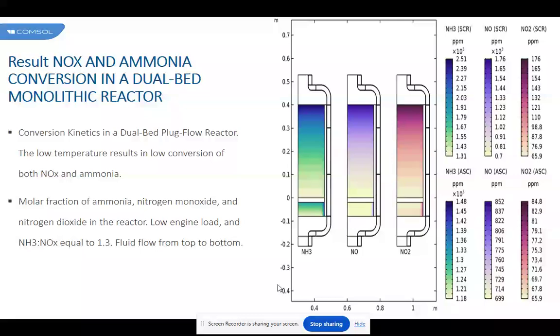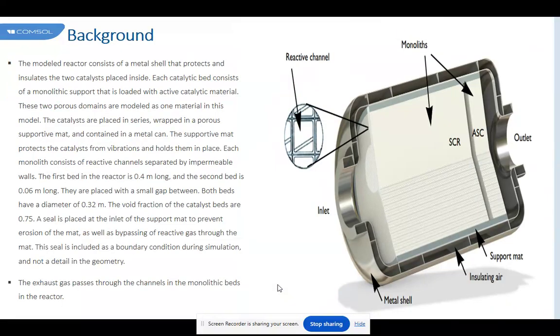The computational model section describes the computational model implemented. A description of the domain. The domain tested was a catalytic converter similar to those tested in experimental rigs. That is an inlet pipe, in this case 1000 millimeters long and 27 millimeters in diameter, followed by a 67 millimeter long diffuser connecting the pipe with a monolith 152 millimeters long and 60 millimeters in diameter.